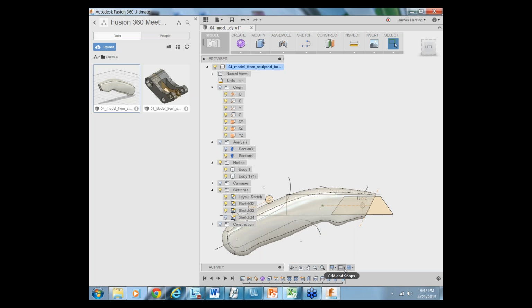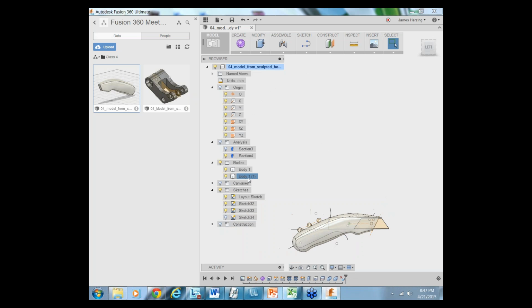So with the cylinder that we extruded in, instead of deleting that, could we have extruded to that surface, the inner surface? Yep, we could have used an extrude to command. I think they were just showing the delete as well as to make it easier to select the surface maybe for the counterbore. That's definitely a good thing to show.